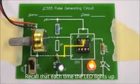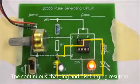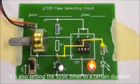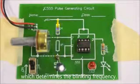Recall that each time the LED lights up is due to the discharging of the capacitor. The continuous charging and discharging results in the blinking. Note that by adjusting the potentiometer, it is also setting the 555 IC timer to a certain duration which determines the blinking frequency.